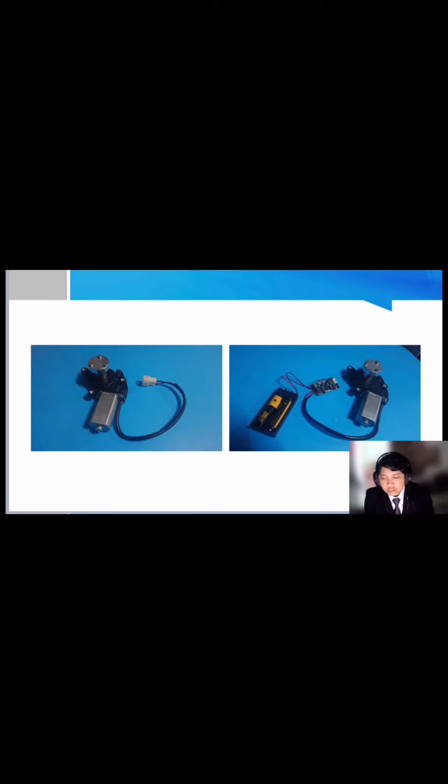Next, the second picture shows the other tools used, such as rechargeable battery, motor driver, power window, and wire. The motor driver acts as an interface between the motor and the control circuit. The motor requires a high amount of current while the control circuit works at a low current signal. So the function of the motor driver is to take a low current control signal and turn it into a higher current signal that can drive the motor.